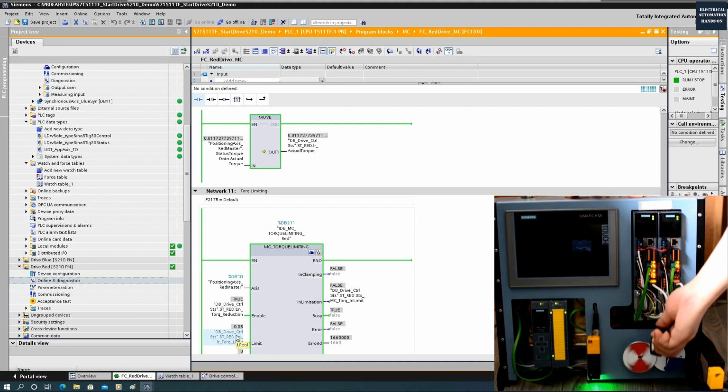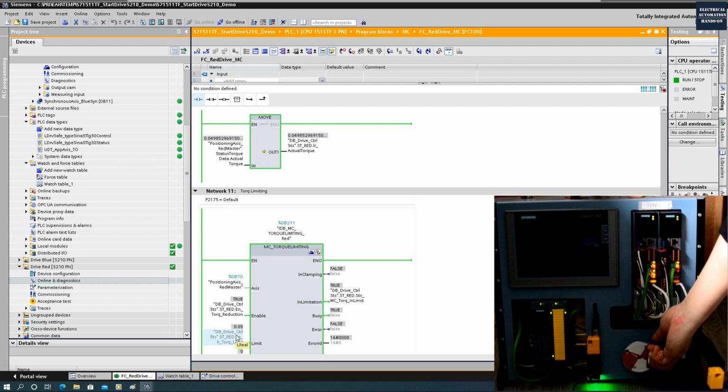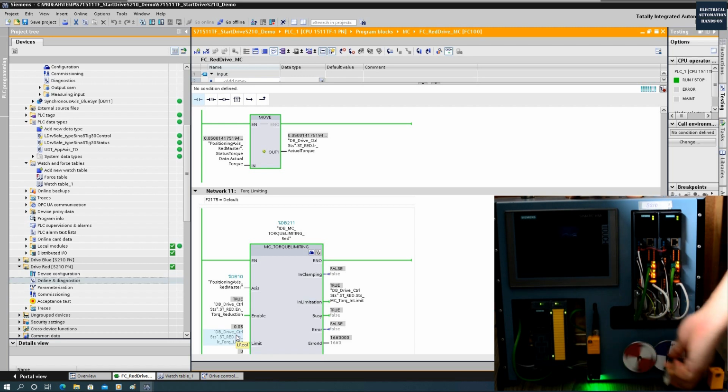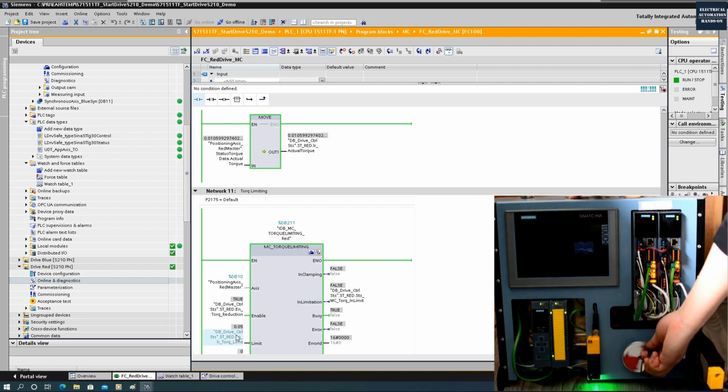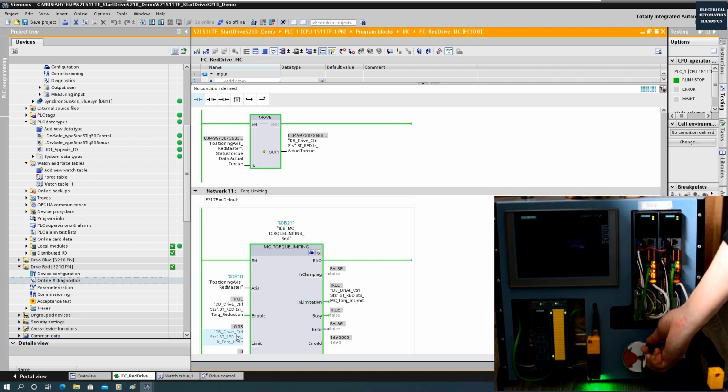Okay, apply. Okay, in limiting, and the highest torque is 0.05. Release. Apply. So while I'm applying load and while the motor is jammed, we will see the in limitation turn on, and the torque value is 0.05. You get this highest range.